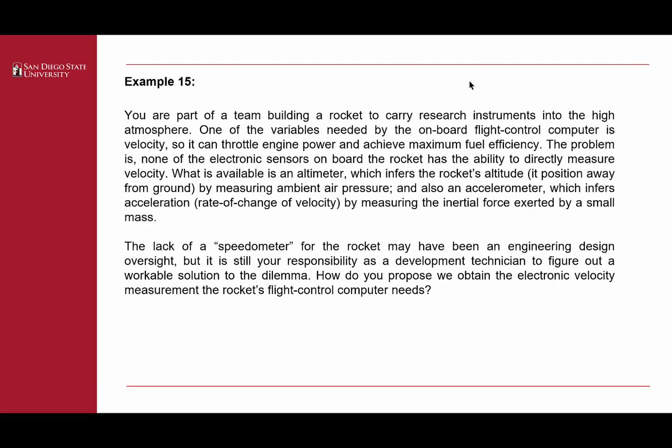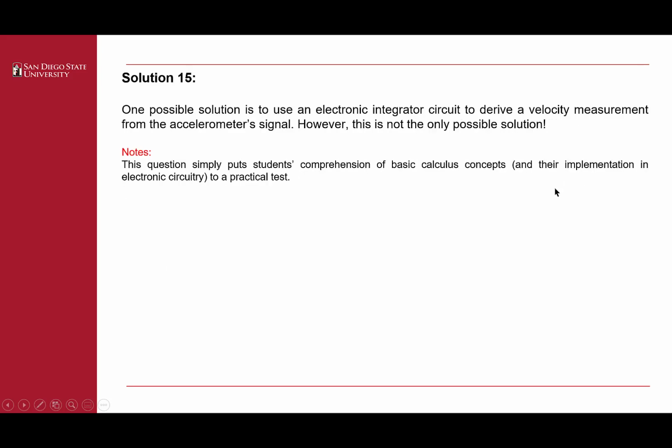You can stop the video here and think about that for a few moments. One possible solution is to use an electronic integrator circuit, as we have seen previously, to derive a velocity measurement from the accelerometer's signal. However, of course, this is not the only possible solution.